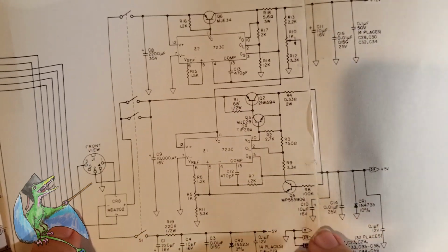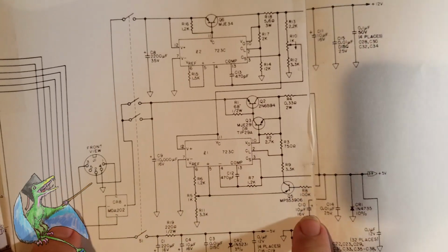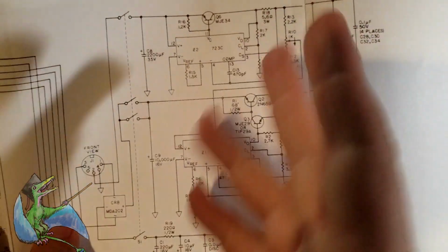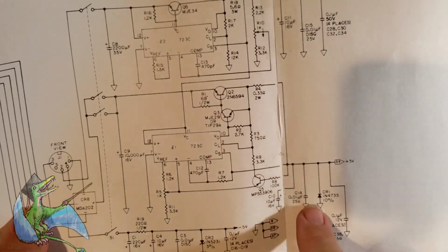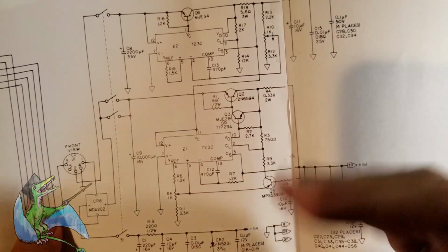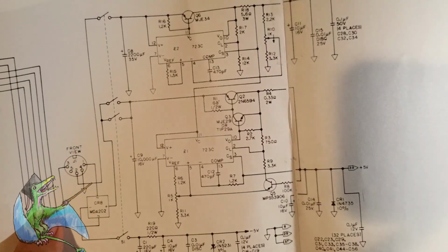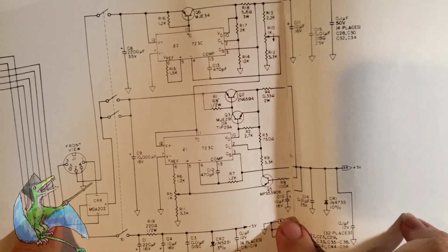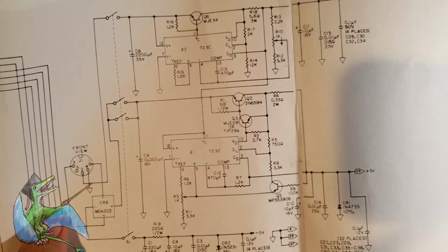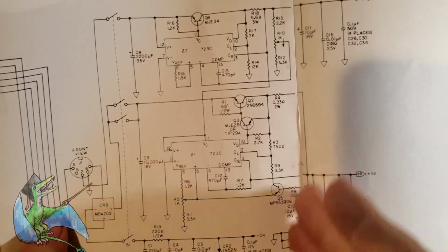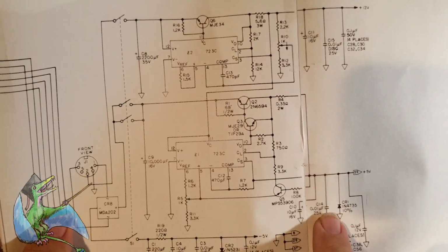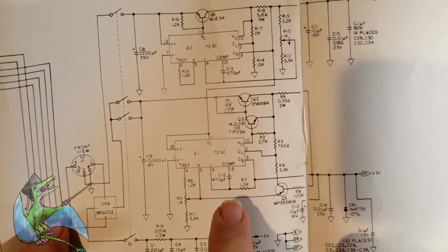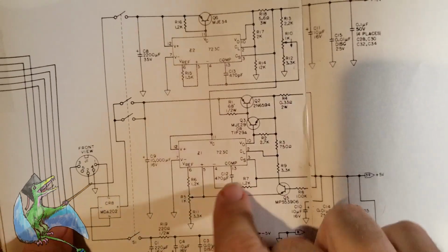The reason for this is for bulk slow transients, like if there's any 60 hertz wave going through. And the smaller one is meant to damp down higher speed transients. I doubt it's the electrolytic can, because the frequency of this would be too high for an electrolytic can like that to help much. It could be C14, but my money is on C13, or at least I think it's the place to start.